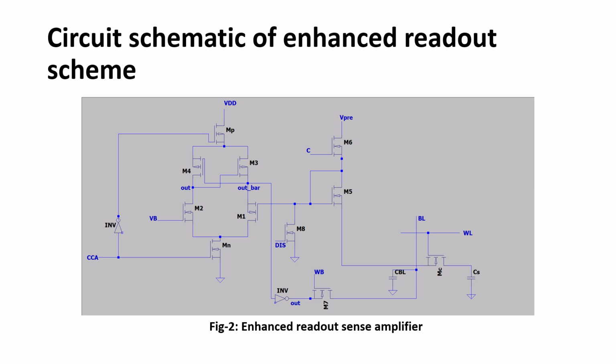If any voltage is present at the initial start of this overall operation, we will provide this signal to this transistor. This will act like a switch, which we will potentially give a very high W by L to discharge this node fast. So when we assert this signal, the node voltage, whatever it is initially before the start of the operation, will discharge to the ground.